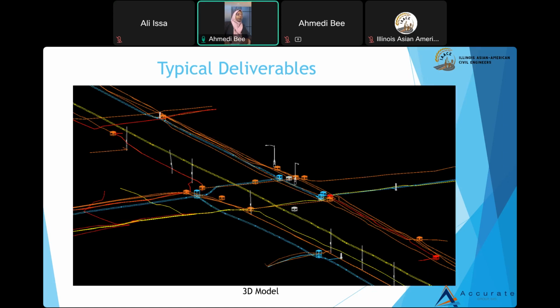and the designer also. So an additional advantage of having SUE information, not necessarily that the whole information would be correct for the 3D, but we can generate a 3D model based on the horizontal information from QLB. Since it gives you the actual location of the horizontal, it is very accurate for the horizontal information. We can generate the 3D model in both OpenRoads and in GeoPak that can be used to develop your cross sections.